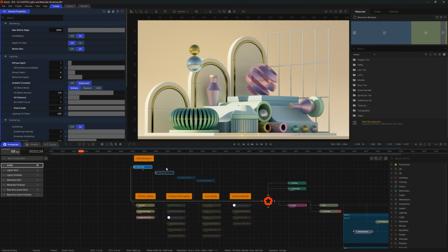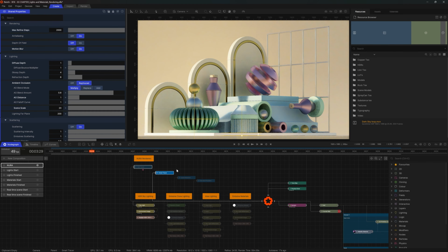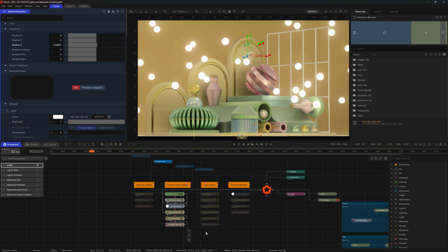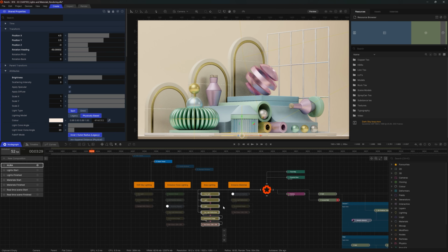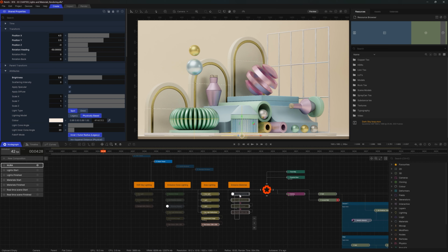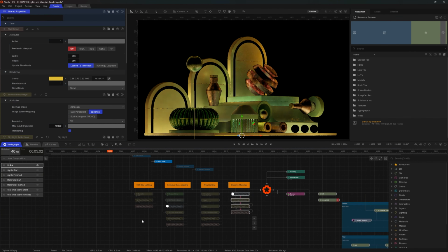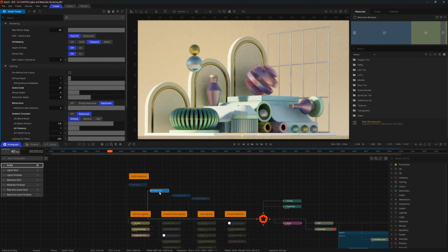Next up, we have the smart tracer. This is essentially our path tracer with a speed boost, bringing the new levels of interactivity and performance using the latest GPU-based ray tracing acceleration algorithms. The smart tracer is built on cutting-edge ray tracing research. It uses many of the same lighting calculations as the path tracer, but accelerates them using spatio-temporal path guiding and reuse via raster. This dramatically reduces the number of passes required for final quality render, from thousands to tens or even just one in some cases.